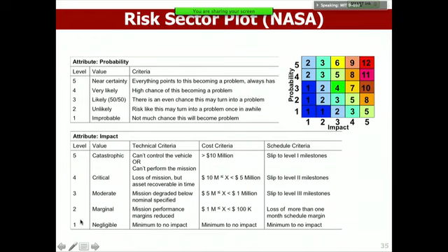So a level 1 impact is negligible. It has almost no impact. A level 2 means your mission performance margins are reduced on the technical side. It means your reserves. Do you remember margins? I asked you to assign margins in assignment A2. So it means you're eating into your reserves, but you should still be able to meet all your performance. There should be no visible impact. Your safety cushion is less. That's what level 2 means.